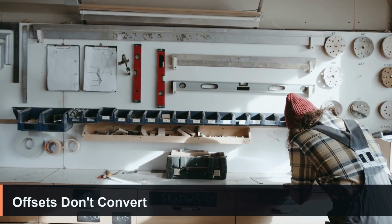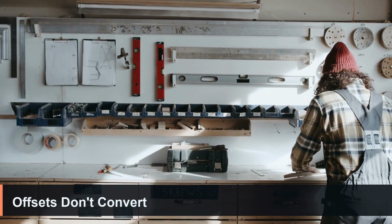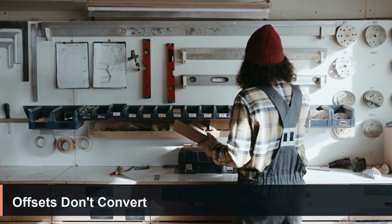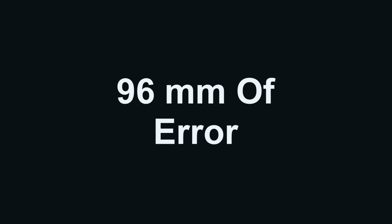There's one more trap. Offsets, tool length, work offsets, wear values. They're all stored in the controller's current unit system. Switch from G20 to G21 mid-shift and your offset table doesn't convert. It just reinterprets. A tool length of 4.0000 in inch mode becomes 4.000 millimeters in metric mode the instant you switch. That's a 96mm error on a single tool. The controller will happily drive it into the table.